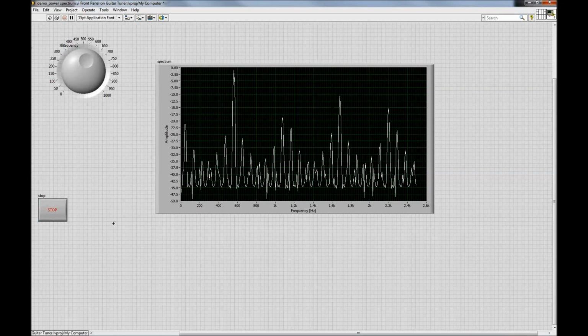All right. So this is the power spectrum for a square wave, right? You can see at almost all frequencies there is a significant component of the amplitude, and there is no clear peak as such, but around 550 Hertz you can see a peak which is greater in magnitude as compared to other peaks. So this is the fundamental frequency, and all the other peaks that you see are the harmonics, or the other frequencies that are also present, which make up this square wave. All right, so let's look at some other demos now.